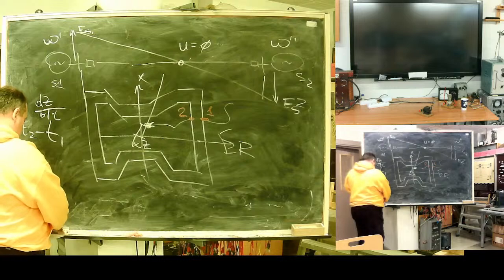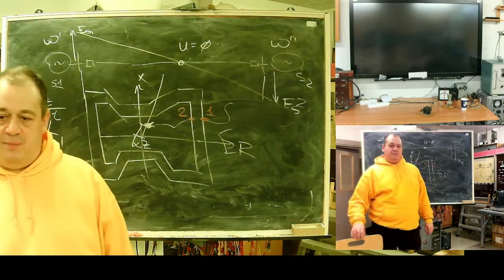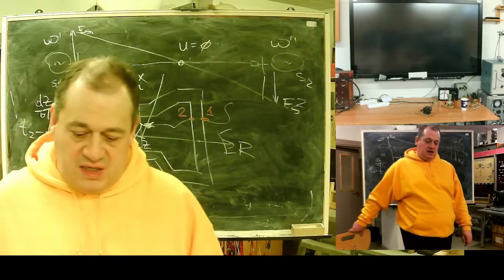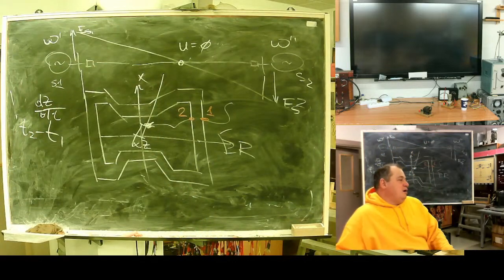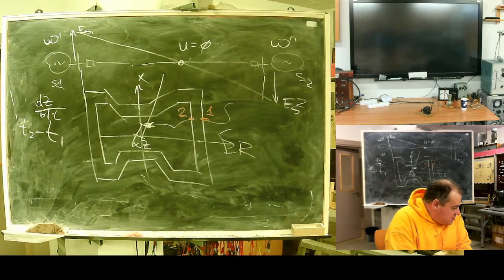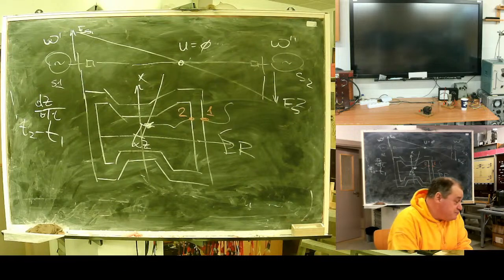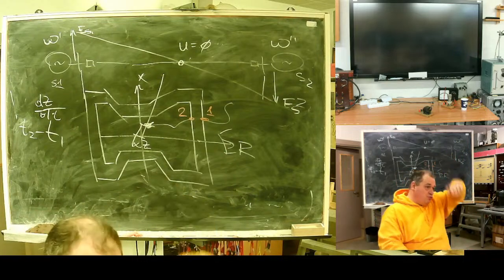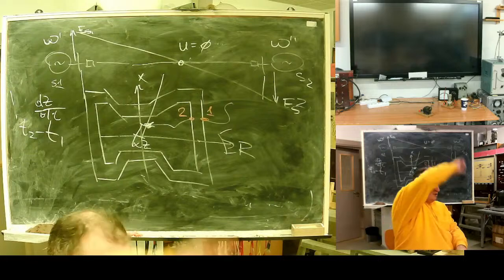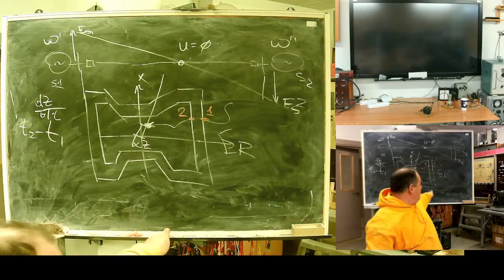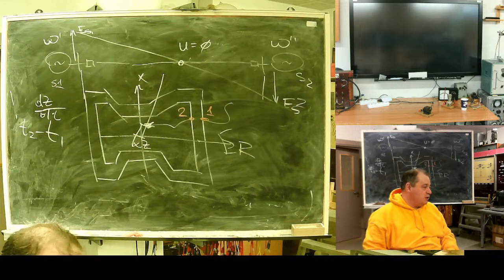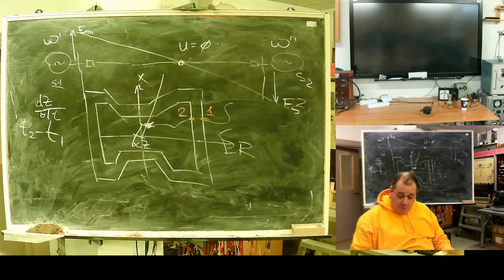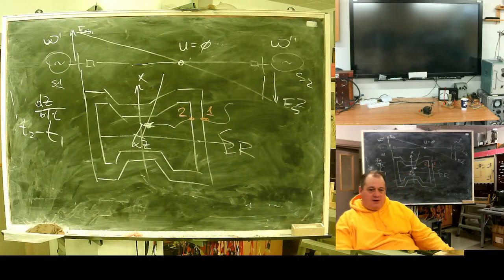Without it, bad things will happen. 100% guarantee. Not even a frequency emergency, a frequency disaster. Also, during connection of a power plant: when a power plant is synchronized to the network, at some moment it swings and then stabilizes. During this, without power swing protection, distance protection will disconnect the line. Oh, bye-bye bonuses. Really.